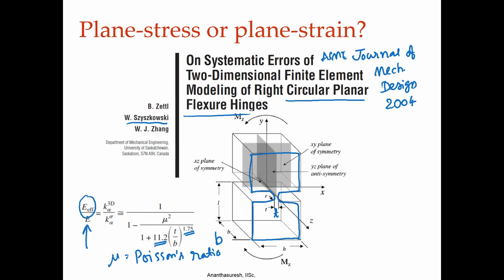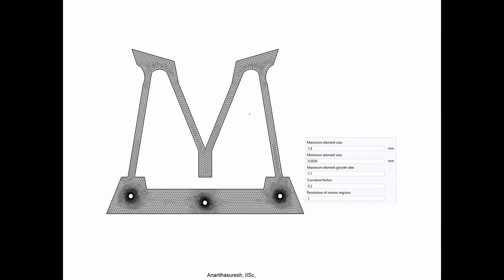Okay. Now, let us look at some compliant mechanism where there is a very fine mesh that is taken, where the force is there. This is the input force, I can call it F in. It is like a crimping device. If you have an object, it will crush that or apply force on it. So, displacement is here, this is the U out. When I take something like this, I can do linear and nonlinear analysis.